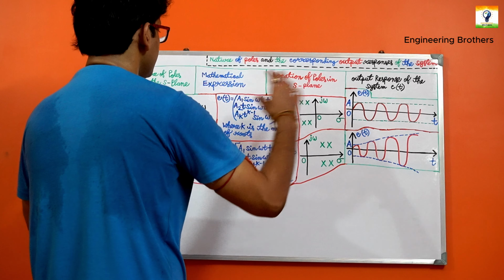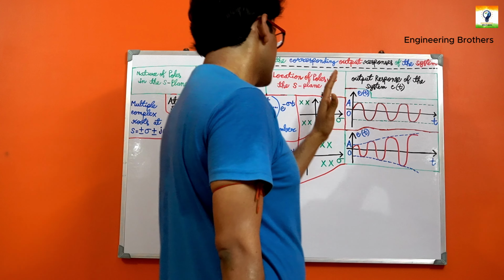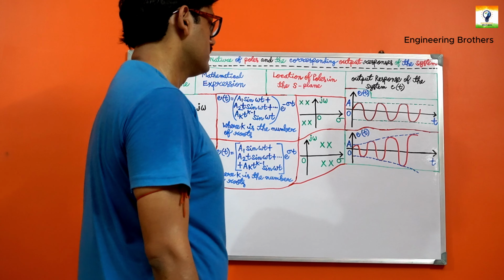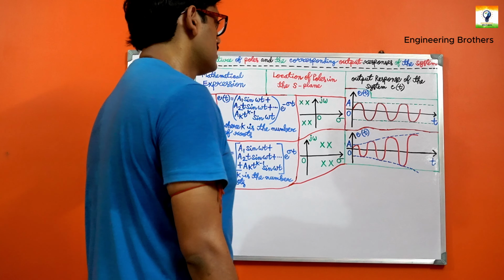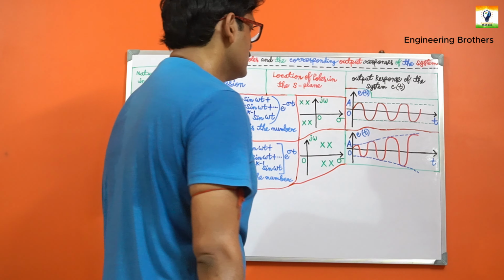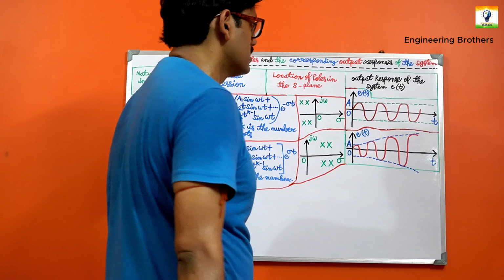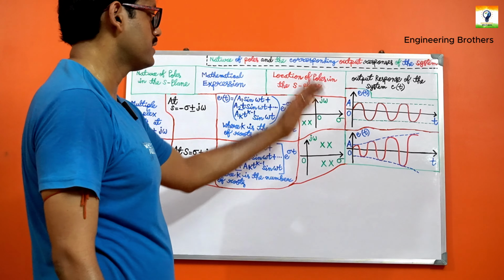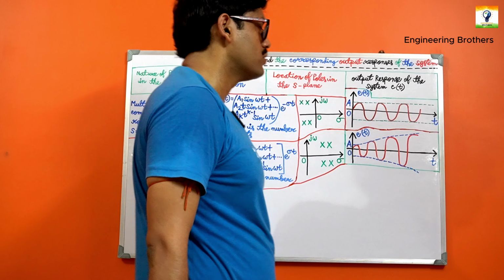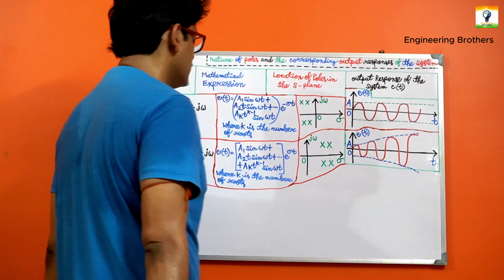Now how do we comment on the exact stability for the given case? Once again, the poles are placed on the left hand side of the s-plane, but that is not the only factor. We should also consider the c(t) versus time curve, which is the output response of the system. By analyzing these two considerations, we can comment on the stability of the system.